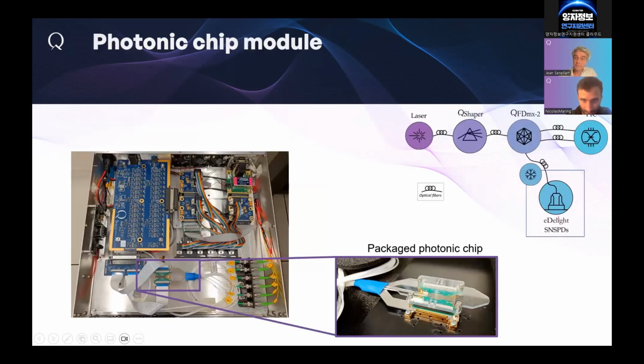Okay. I can show you also the photonic chip. This is a small photonic integrated circuit that is packaged. You have the fibers input and output here on the chip, and all the electronics control, so the different phase shifters that are actually controlled by also a Quandela driver, and a lot of different electronics. What you have here, for example, is polarization control of every fiber at the input and output of the chip.